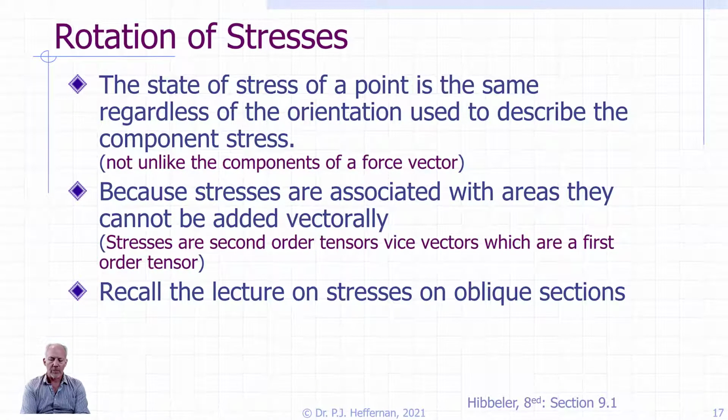Well, it's not really that much different for stresses. Our orientation that we're working in is typically chosen out of convenience to the mechanics, right? So along the axis of the beam and parallel to it, up, down. And so that axis is one simply of convenience. But what we need to do is now change our orientation or consider alternative orientations, which is going to change our description of the stress state. It doesn't change the stress state, it just changes our description of the stress state so that we get it in a manner which describes it in the worst possible case, which is to say, what are our maximum normal stresses? What is our maximum shear stress that occurs at that point at some angle theta?